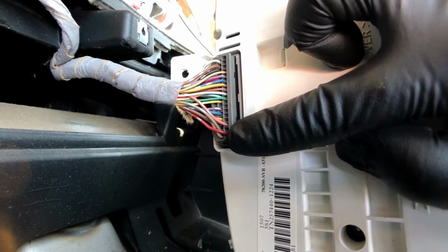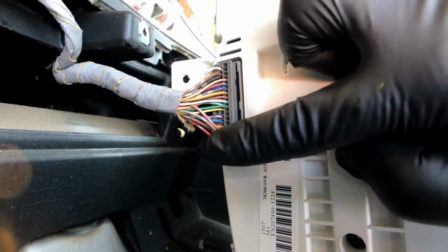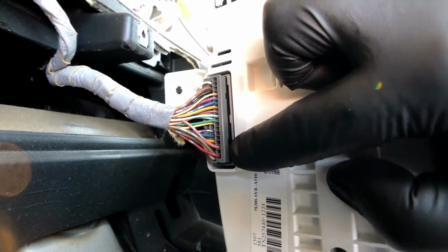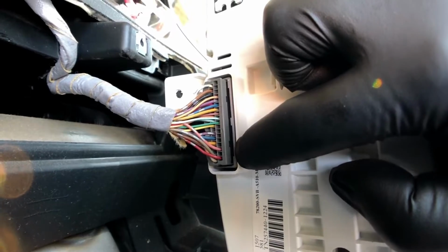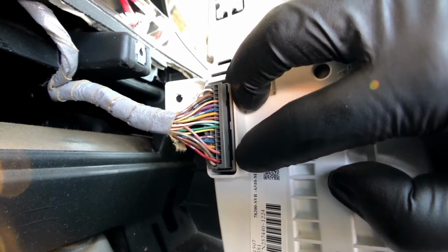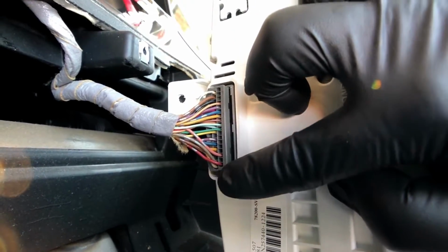So I'm gonna back probe pin 1 and pin 19, which is the white and the red right here, and see what I have. I want to see the signals. I'm just curious to see what they look like. And if I don't see anything there, then I'm gonna unplug it, and then I'm gonna get an ohm meter